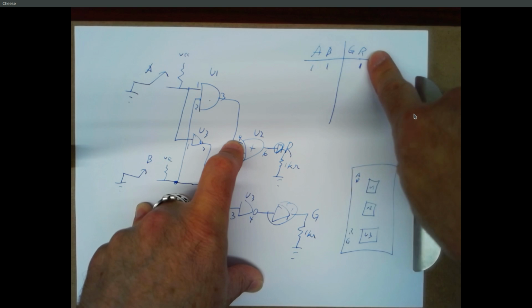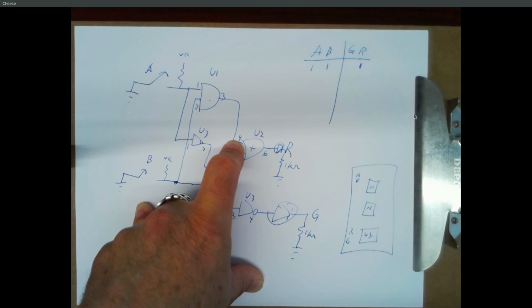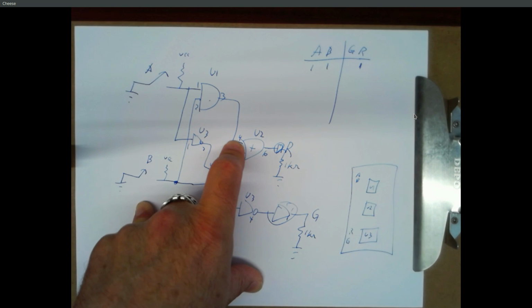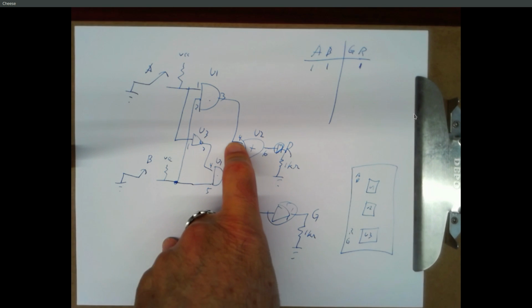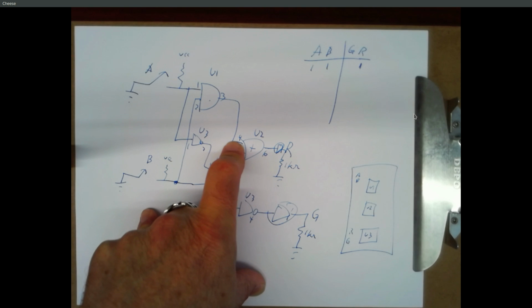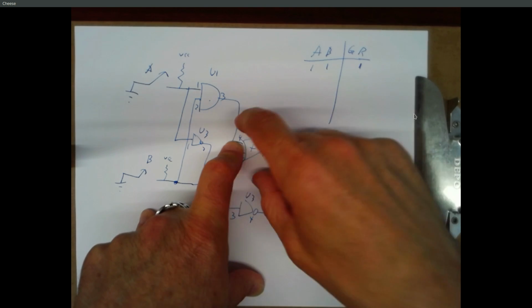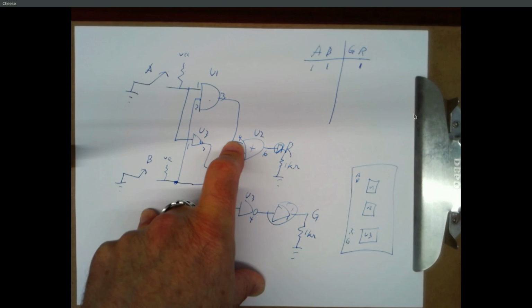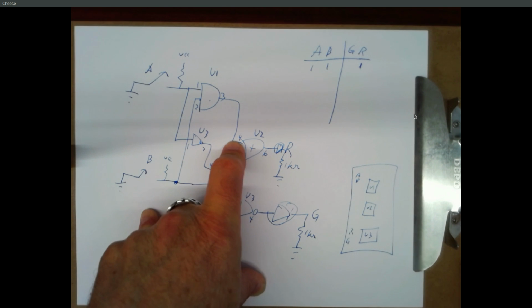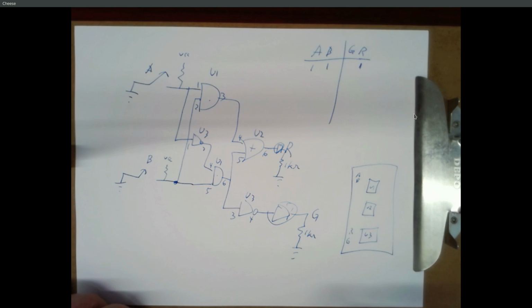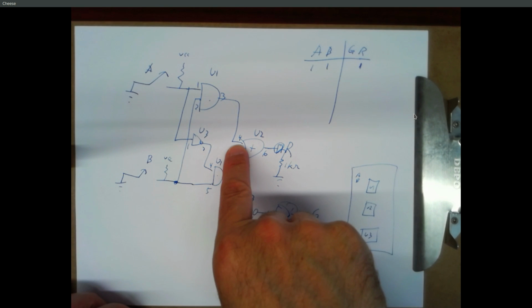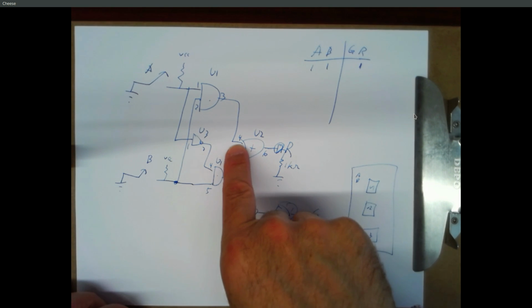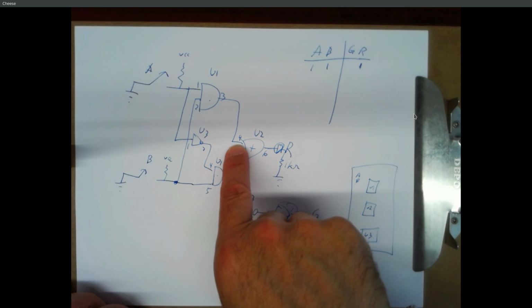That's kind of it. So look at where power and ground are, take voltage readings there, should see 0 volts, 5 volts. Read the number on the top, make sure it says 74 LS, whatever an OR gate is. And if all of that looks correct, try a different OR gate. And you pop this one out and you say, oh, pin 7 is broken, right? So it wasn't getting power, so you put another OR gate in. But if this is a 0 and I believed it should be a 1, that's a problem, right? So where does this come from?